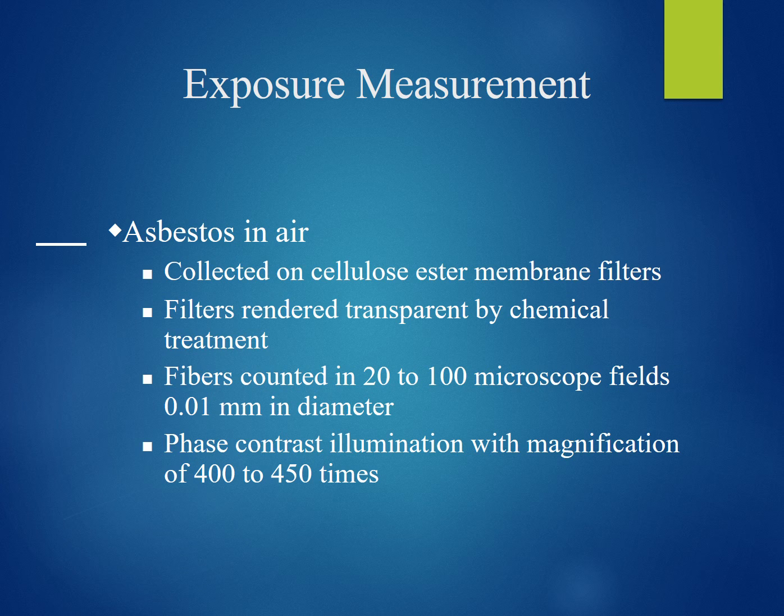To collect asbestos samples or other fibrous minerals such as fiberglass or mineral wool, use a specific filter, and the fibers are counted using a microscopic method. This counting is similar to how we used to count blood cells in a pathology lab.